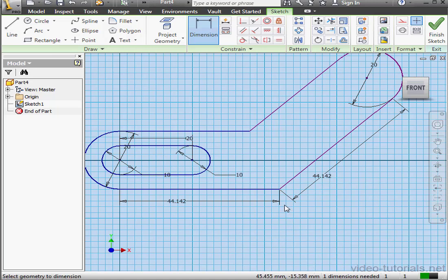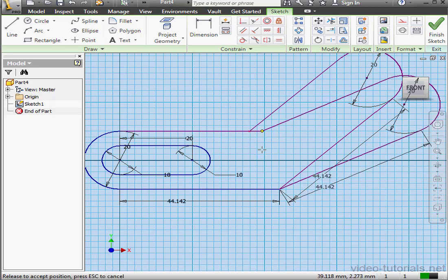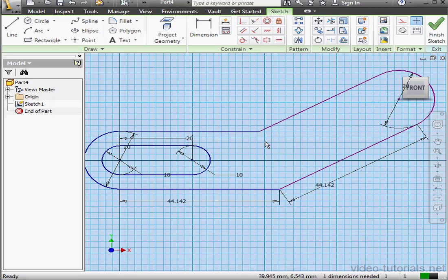We already know that to figure out what's missing, I can simply grab and drag my geometry around. Let's escape to exit this tool. I'll grab this point and try to move it. I'm not able to. It is fully constrained. Let's try to do the same thing over here. And now we know we need to apply an angular dimension. Let's undo that move.